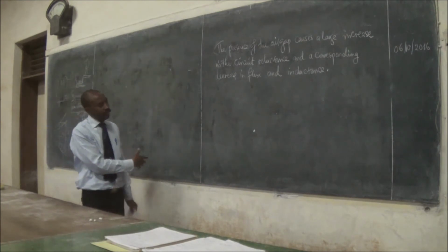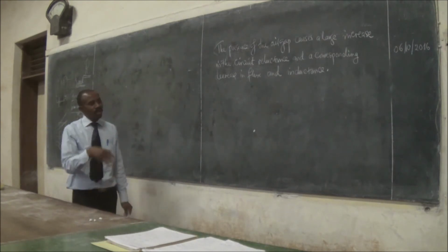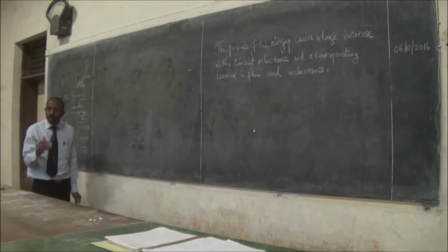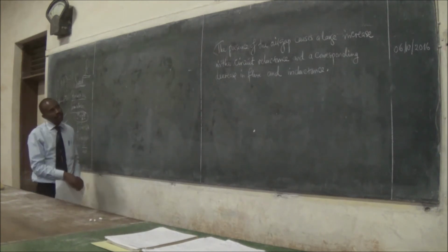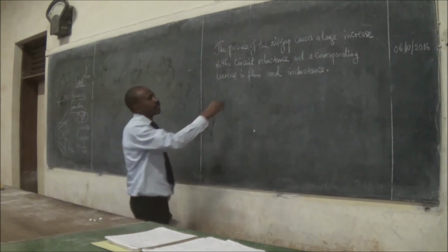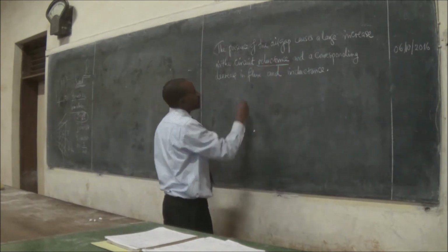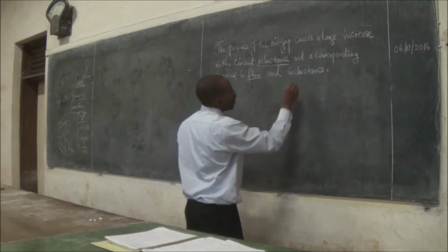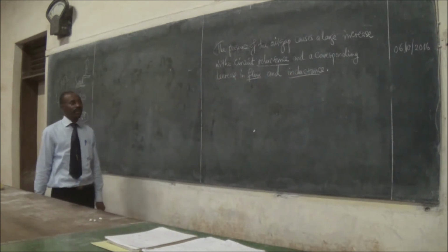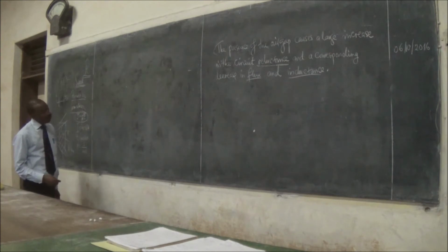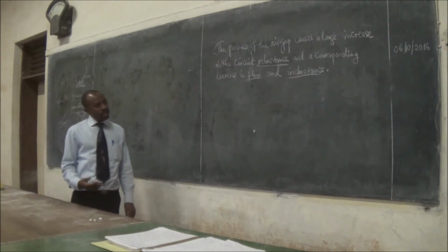From these simple circuits, if you were able to chop up that part and create a gap, you would interfere with the reluctance. And when you interfere with the reluctance, you can change the flux. Then you can also change the inductance. And the flux, thinking from Faraday's law, it is all about flux.